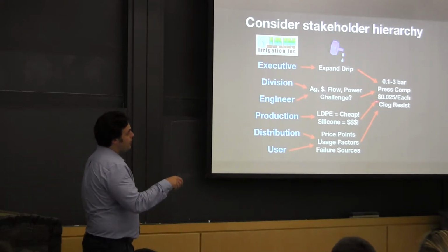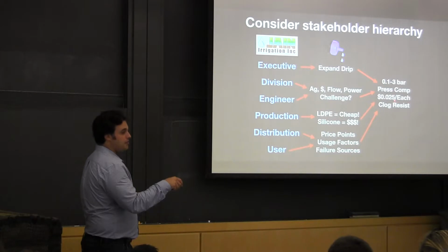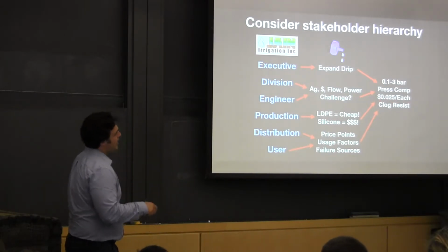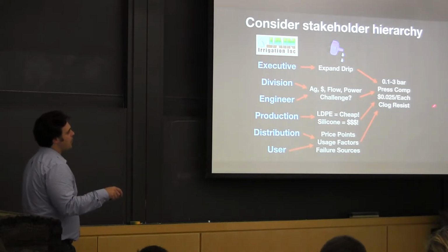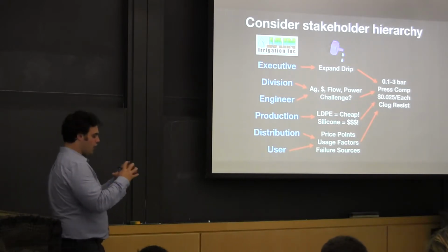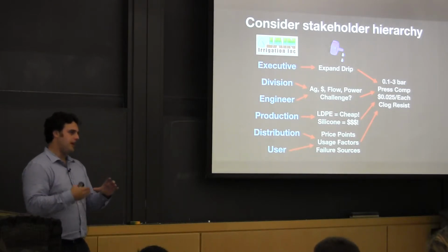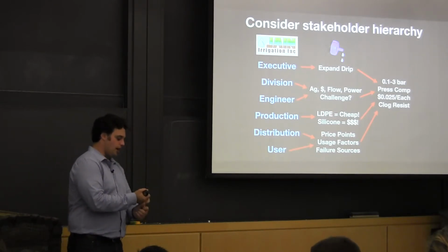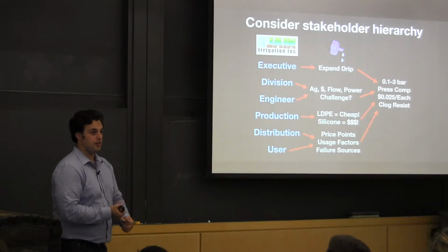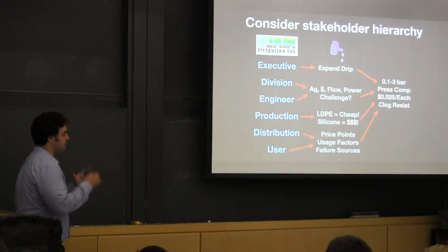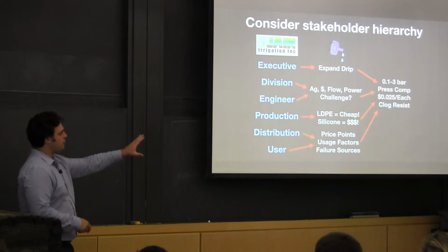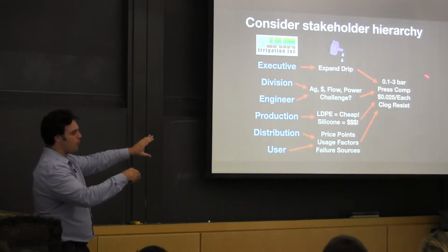We knew the price point of each dripper because we need about up to $5,000 per an acre field, so 2.5 cents each was the limit. And we knew that if we could make it clog resistant by having large internal flow channels, we'd need less filtration, and filtration causes you pressure loss and capital cost, right? So there's an incentive to make it bigger channeled. So that was really cool. That said, here are our core requirements, right?